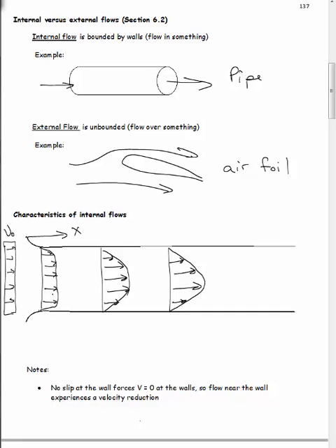Okay, the area here, if we're looking down at the entrance part here, there's only a little bit of space here where the velocity is changing. Then the velocity is flat. Do you remember where the velocity is changing? There was a term for that. That area, that region, it's called the boundary layer, remember? So all around, right near the pipe surface, you're going to have the boundary layer. Okay, and that boundary layer is going to get bigger as you go along. So if we draw the boundary layer, it's going to go to where it becomes flat, right? Eventually that boundary layer meets in the middle.